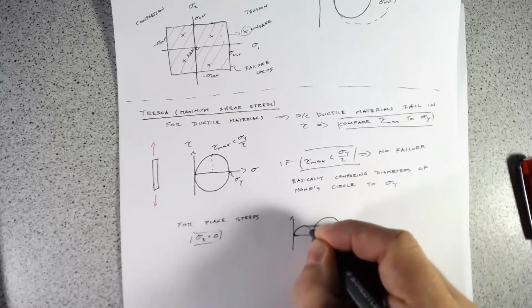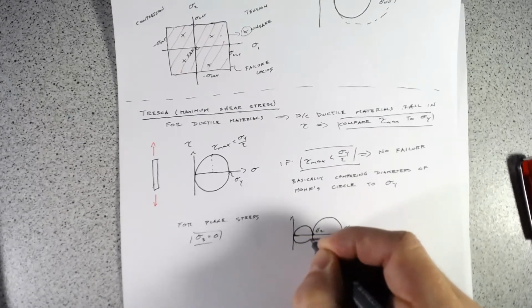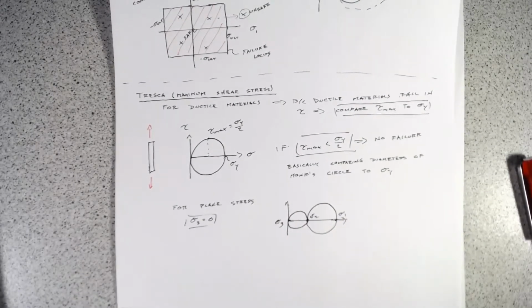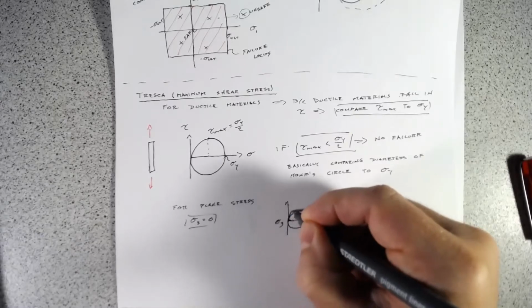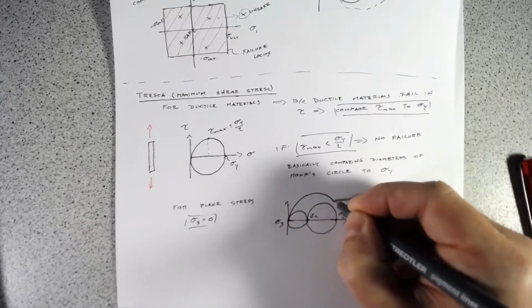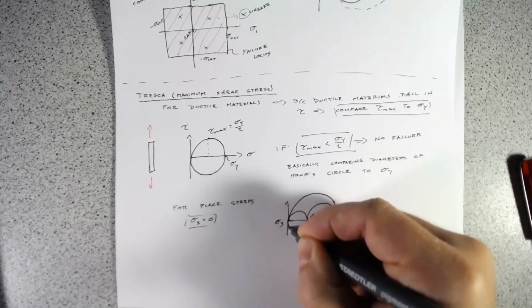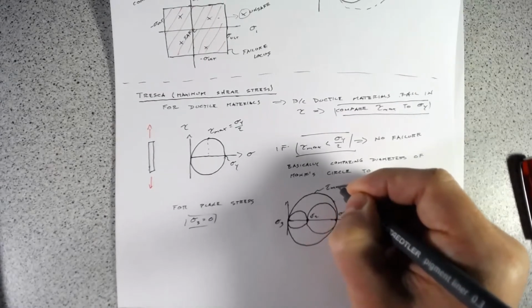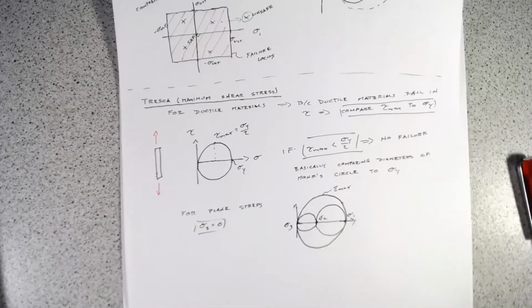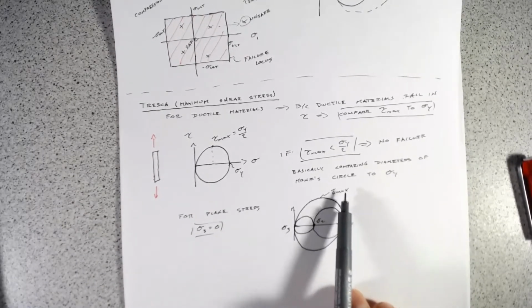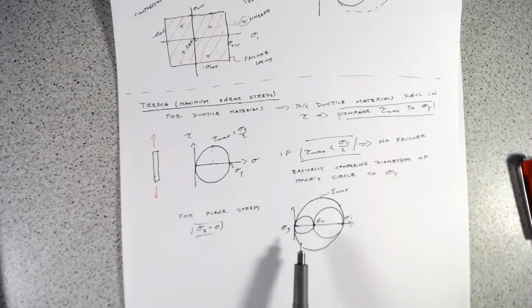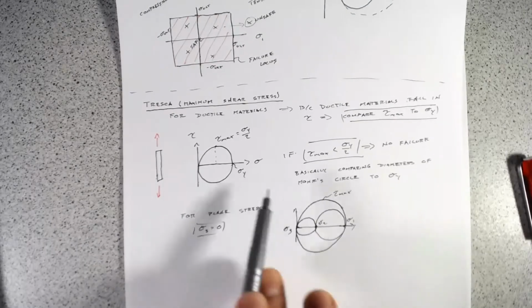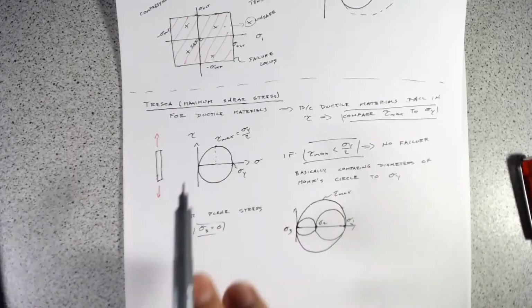And as we talked about in our 3D Mohr circle lecture, we have sigma 3, an orthogonal one over here, and then if we rotate about the sigma 2 axis, we have some tau max up here. But really, what we are more interested in is what is our total diameter of this Mohr circle, and compare it back to sigma y over here, this diameter here.